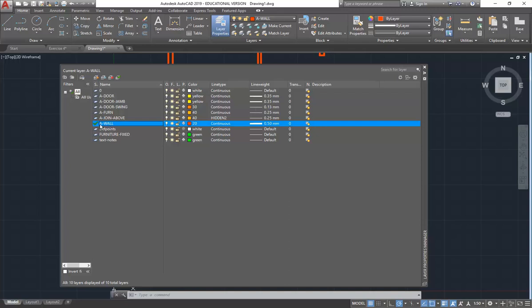So here, this wall layer, that's my nice heavy line, it's 0.5, that's obviously heavy because it's being cut. So I'm going to make another layer called A wall, P-R-O-J, for projection. So a lot of people would rename this one and make that A wall cut. But you don't have to. You can just assume that if it doesn't say it is being cut. So A wall projection. Above or below, if it's not being cut. Yeah. Or not below, behind. Yeah, it can be in front or behind, yeah.